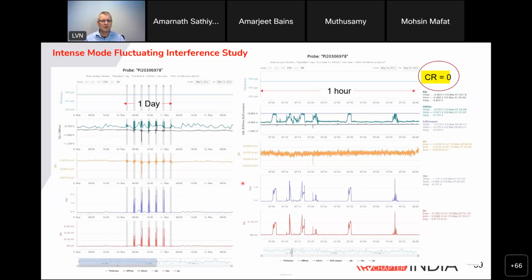These are measurements where we have made an interference study on a fluctuating system where trains come passing by. We measure the electrical fingerprints every 1 second, and throughout the day we can see that if you focus on 1 hour, you can see some electrical trains coming by and giving you some interference. So you can actually read the fingerprint of the train, also like this.